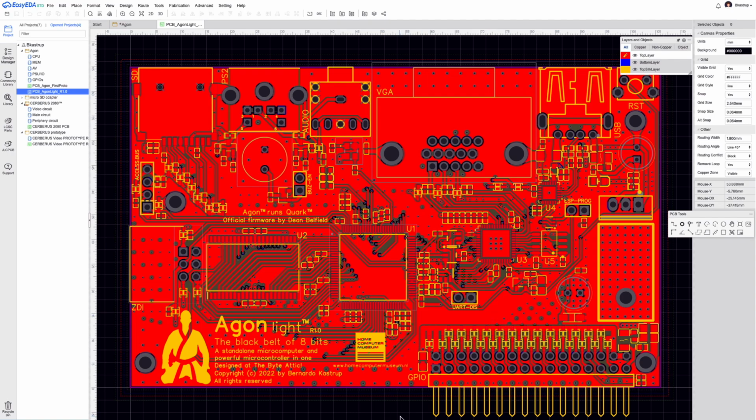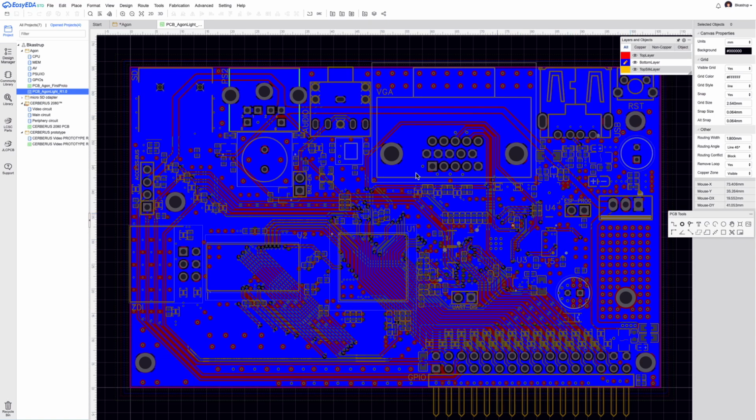So, it costs nothing to add these stitching vias. So I stitched everything. These are VCC stitching vias, and these are ground stitching vias, because the same rationale applies on the other side. On the back of the board, the bottom layer is copper flooded with ground, so you need to connect this. These are the vias that you see there, and where else? Here. You need to connect them to the ground plane, which is inner 1.